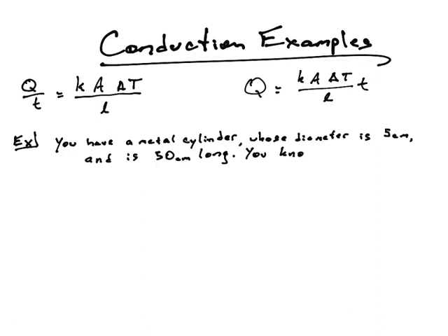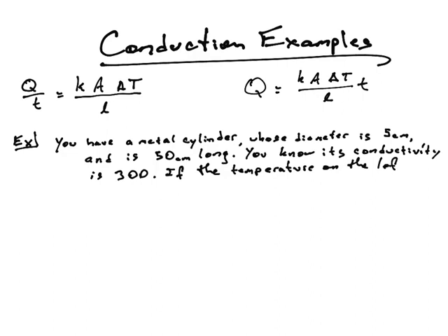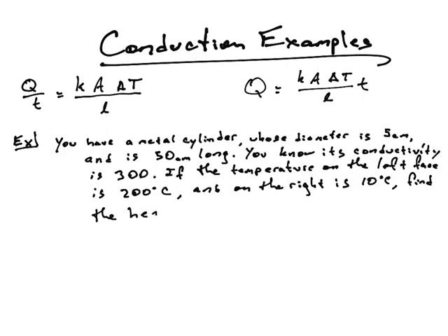You know its conductivity is 300. If the temperature on the left face is 200 degrees Celsius, and on the right is, let's say, 10 degrees Celsius, find the heat transfer rate through the metal.